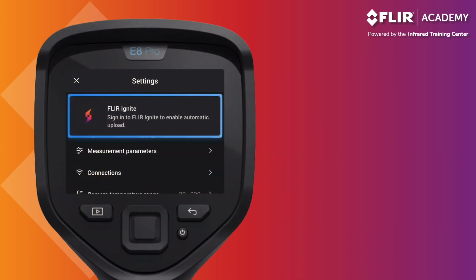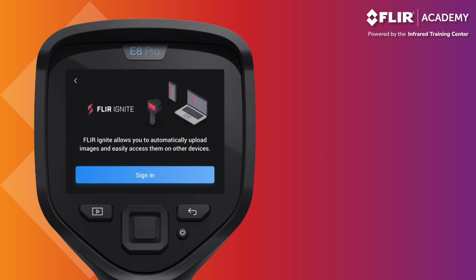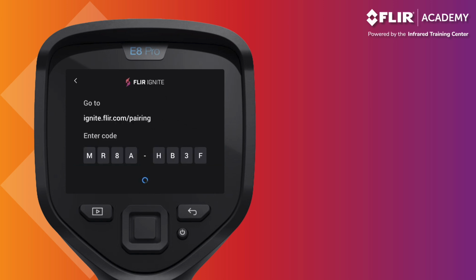To pair your thermal imager with an Ignite account, navigate to the camera Settings menu and tap the FLIR Ignite option at the top of the screen. Select Sign In. Here you will see two options to connect a camera. A URL is available if you prefer to do this via a web browser, or you can use your smartphone camera to scan the QR code. Let's do that for the purposes of this demonstration.